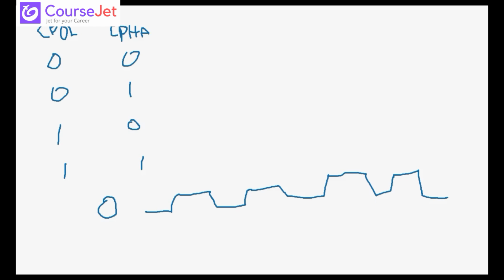In this SPI mode 0, 0, 0, the concept will be that it reads on rising edge and changes on falling edge. Read on rising edge and change on falling edge, which means what?